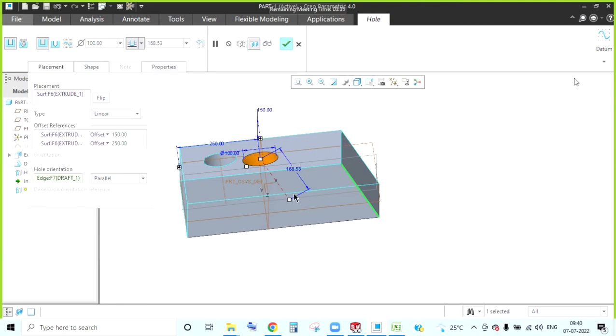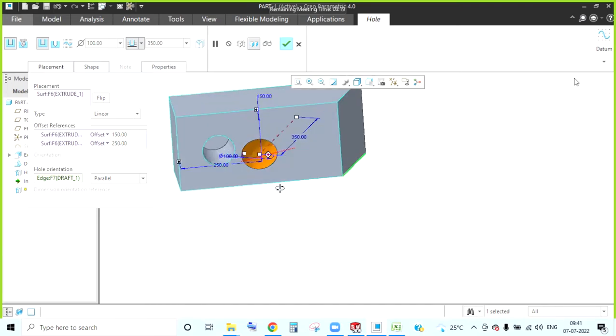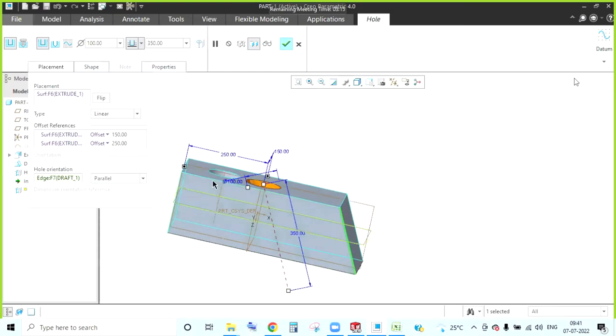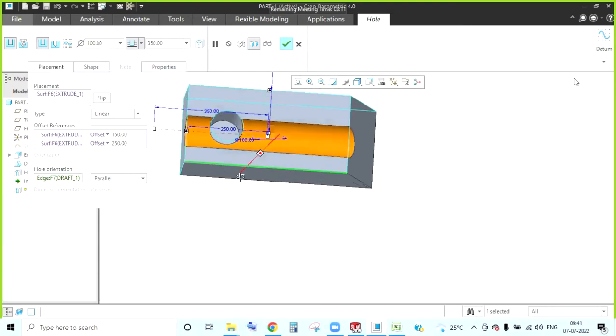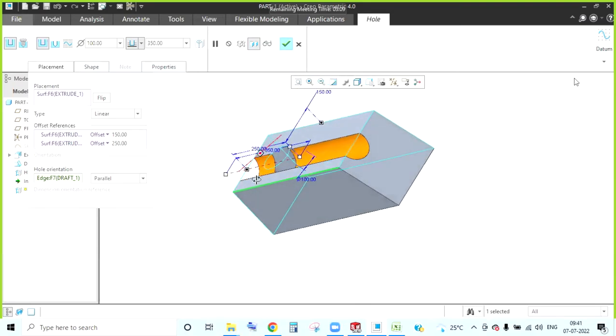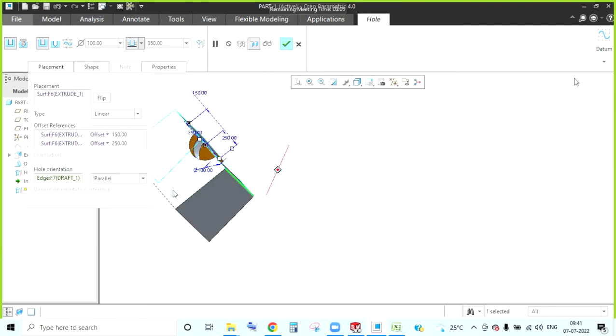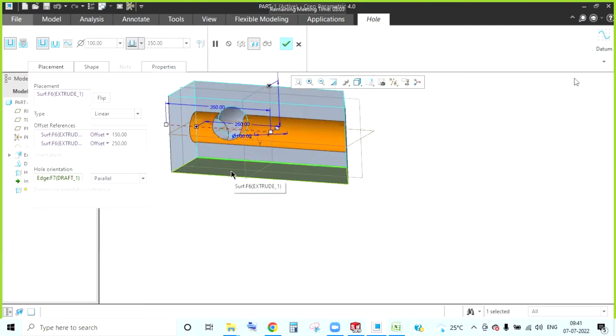Right now, my hole direction has been changed. I'll change the value of the hole so that you can change 250, 250, to 350, 350. You see, the hole direction has been changed. Literally, I can even give this. You can see. There is no need for me to make a sketch here. Simply, I'll make a hole and I'll change the direction automatically. It will be giving it.